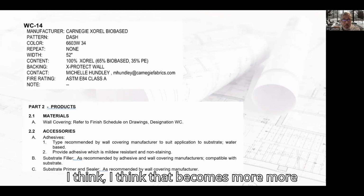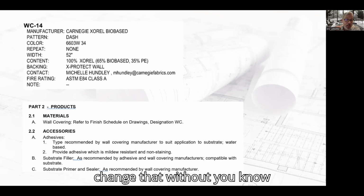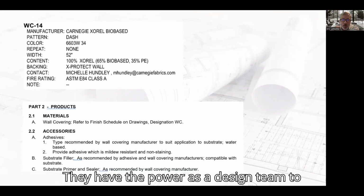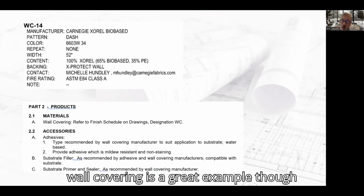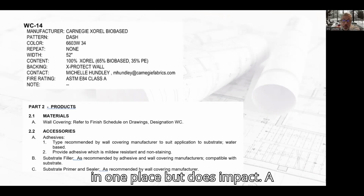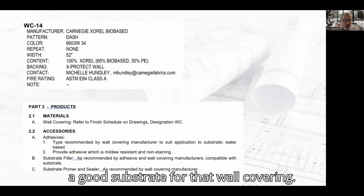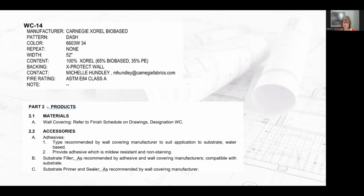Yeah, I think that becomes more important for independent specifiers, to give the design team the power to change that without forcing something into the spec that they then have to go back to the spec to change. They have the power as a design team to answer those questions during the next phase. I think wall covering is a great example, though, of something that is specified in one place but does impact a different section, because it requires a level 5 drywall finish to get a good substrate for that wall covering. So you get something in one paragraph, one section, that does affect another section.